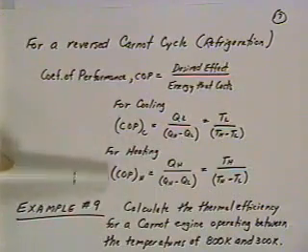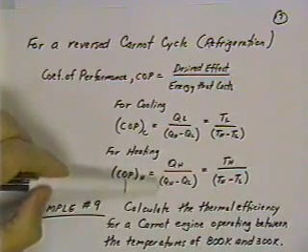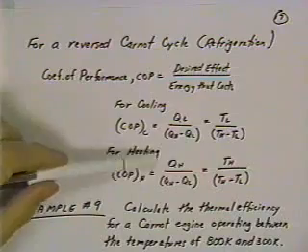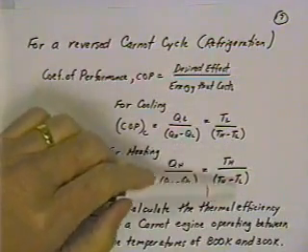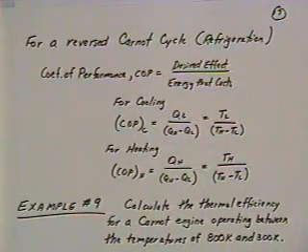And for heating, you're interested in the heat transfer on the high side, QH over QH minus QL. This, of course, is the work term, so the energy that costs you is the work. And so this then is TH over TH minus TL. Again, TH minus TL is the work term, and TH is the heating. So you have two terms when you're talking about refrigeration cycles that are important to you. One is the coefficient of performance for cooling, defined as TL over TH minus TL, and for heating it is TH over TH minus TL if you're talking about the Carnot cycle.